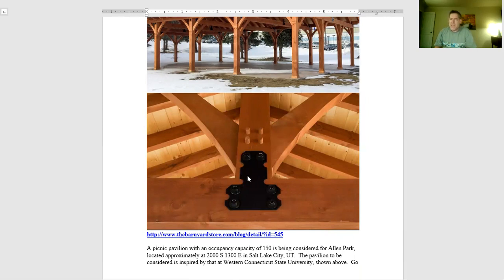The T-plate is on either side of this member, and that tells us the bolts are not at the outer fiber. There's nothing there connecting where sigma equals My over I would be largest. So even though there could be a force couple transfer, it's not going to be very significant. And oh, by the way, you're going to have clearances that are going to be needed to get those bolts through there. This thing is not going to have a lot of restraint to rotation. So for sure, there would be a pin connection of this king post as we model it coming into this joint.